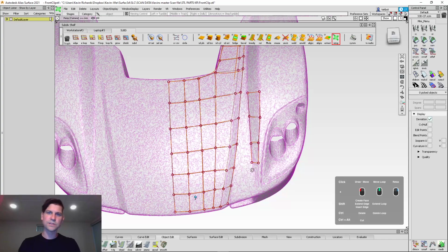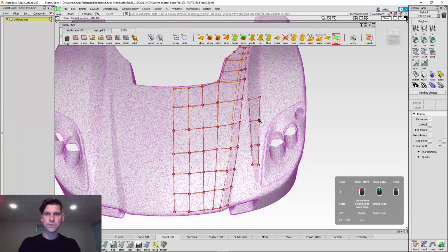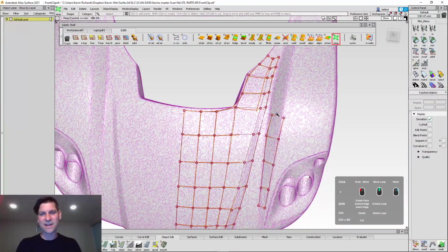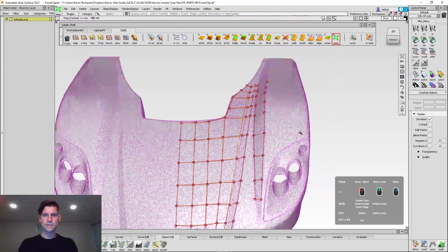So sometimes it just makes sense to stop what you're doing, because I'm about to ruin. No, I'm just kidding. Just to start building these ones separately. And one thing with sub Ds, you always want to basically match the edges. Otherwise, you're going to have to worry about chasing those loops to track them down. So we'll just do something like this and like that. Cool.